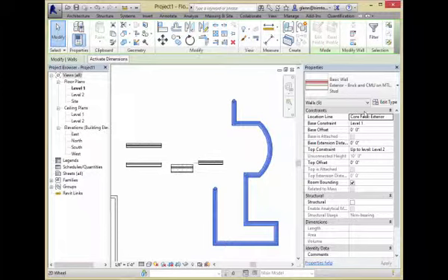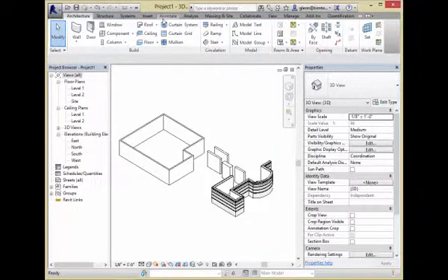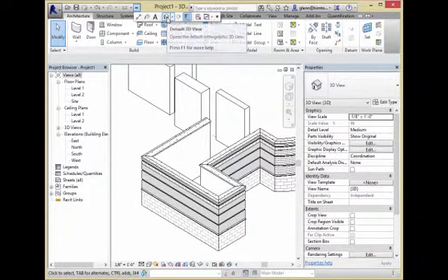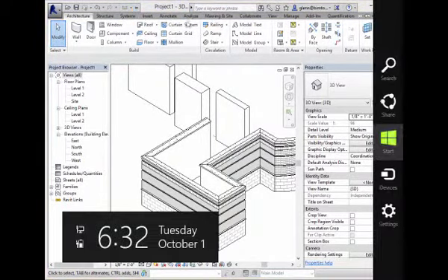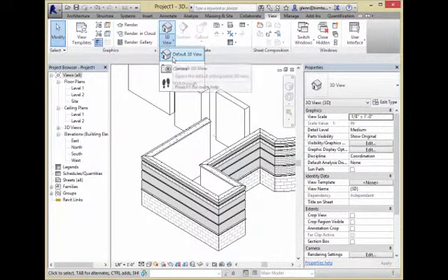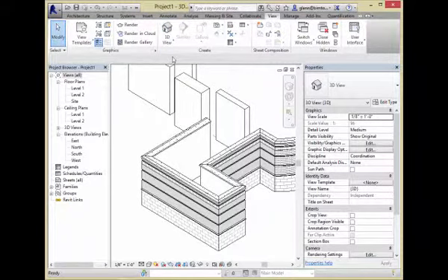The other property we want to tell you about that's an instance property, it's a good one to think about controlling, is just the height of the walls. So let's talk about that. I just switched over to the 3D view. If you don't have a 3D view right now, what you can do is, up here in the top, little quick access tools, there's a little 3D house there typically. You could choose that, and it'll pop open a 3D view. You could also, under View, 3D View, choose the default 3D view. That'll open it too. So if your model doesn't have one yet, make yourself a default 3D view.